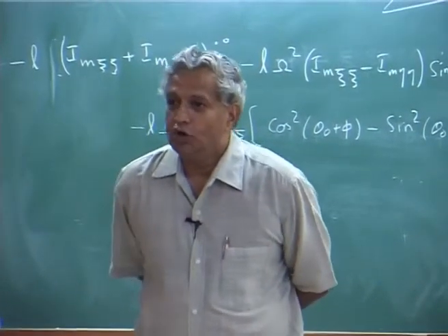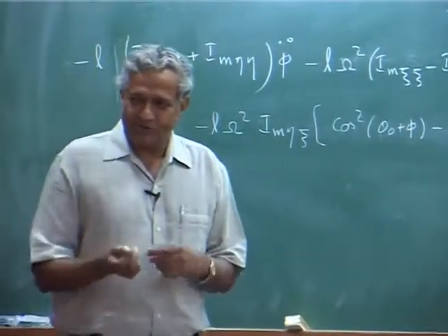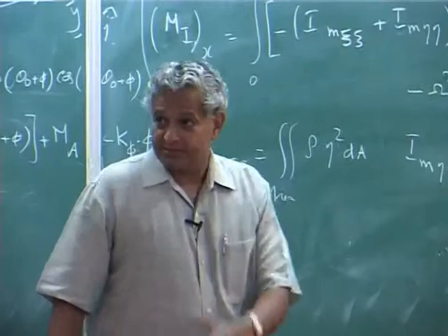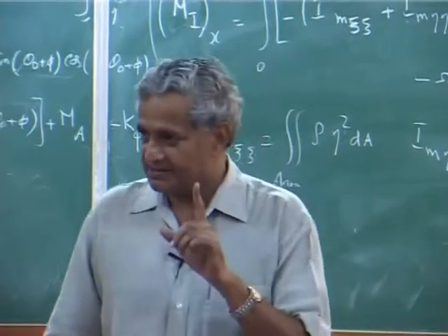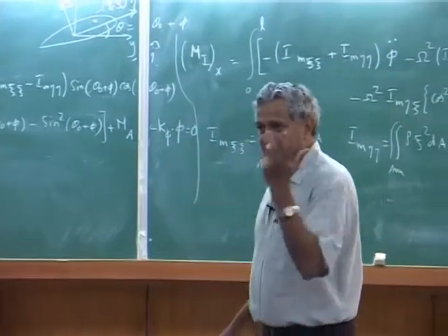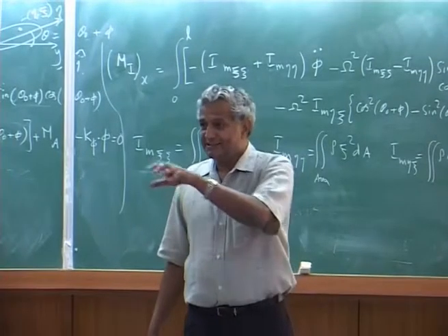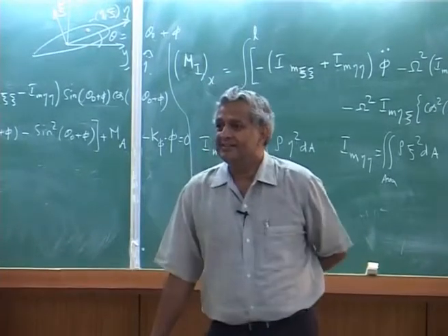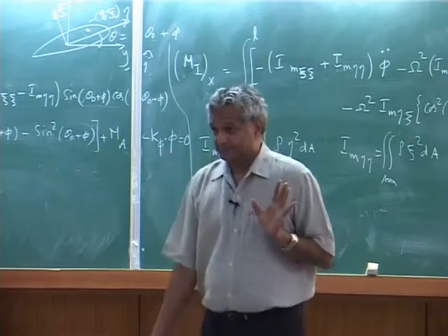Earlier, that includes it. That is why I don't take it separately, because the acceleration at a point, what I wrote as the big expression, it has everything, the Coriolis term, but omega is constant. When you take a rotating beam, you will write the acceleration as four components: relative acceleration, Coriolis acceleration, angular acceleration, centripetal acceleration. That is for ease of things. But if you read this, the derivation follows everything.